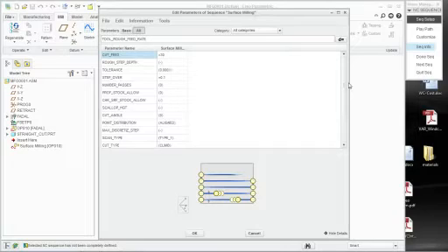So if you have a machine where your coolant is always on, by default in the machining software it's always off. So that's something that you would have to change every single time. So in this case, what you can go into is your site file, make that standard in your site file, apply it, and then that coolant would always be on, and then you don't have to deal with it. Okay, so a really good way to standardize the parameter fill out as far as speed, feed, and depth of cut.